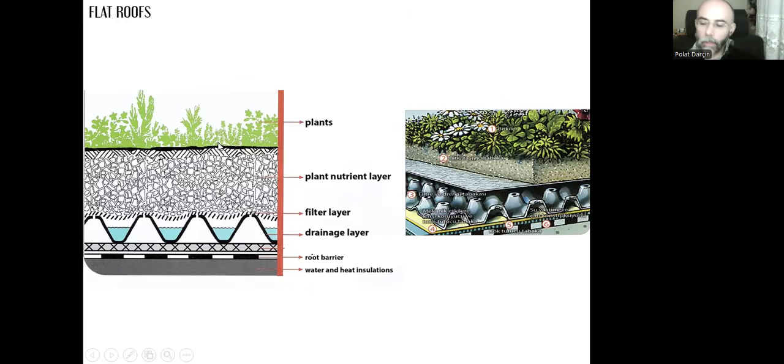But you should keep in mind that this system is pretty heavy, and the thicknesses are important. You don't want very thick layers over your floor, and during their weights, you may need to enhance the structural capabilities of your floor and your building structure as well.